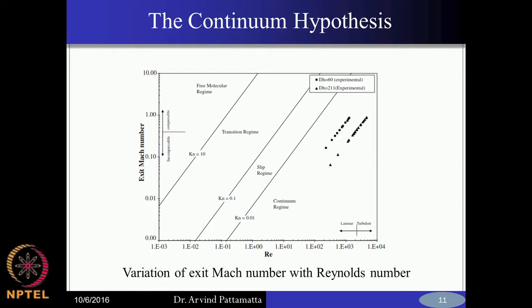Now again, we saw that the Knudsen number is a function of the ratio of Mach number to Reynolds number. So, we can again classify all these regimes. Rather than looking at only the Knudsen number, we can plot Mach number on one axis and Reynolds number on the other, and classify these regimes. And not only that, it also depends on what kind of equations you want to solve. The Navier-Stokes equations can be compressible or incompressible. We did not discuss that. That can be analyzed when you also plot the Mach number and then decide where you are standing.